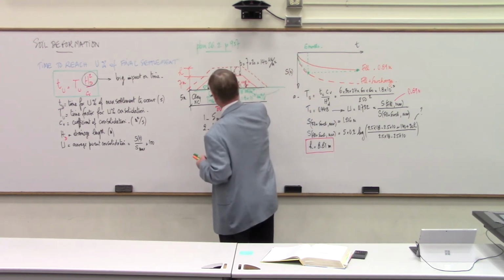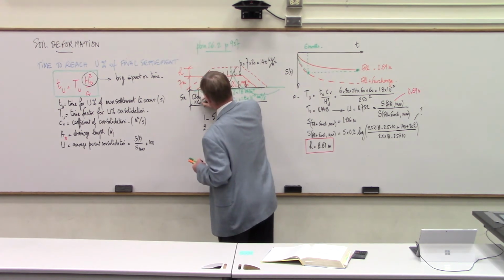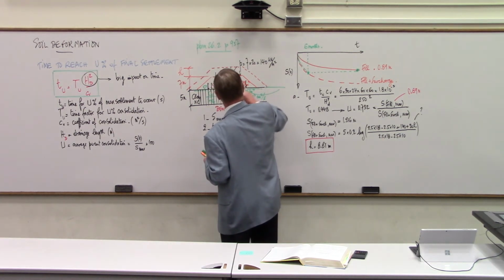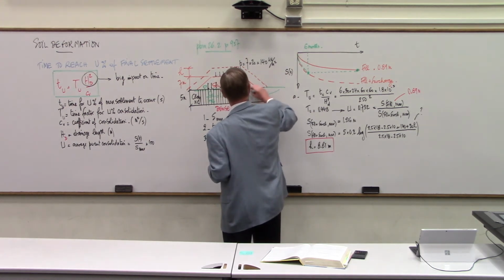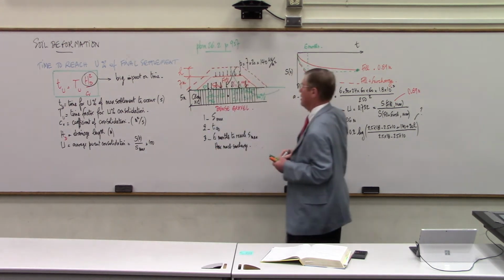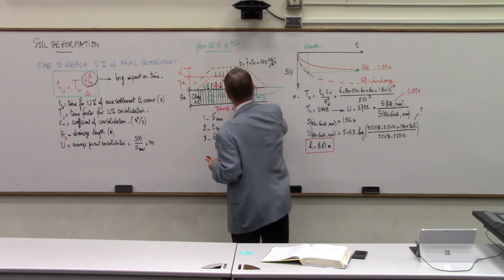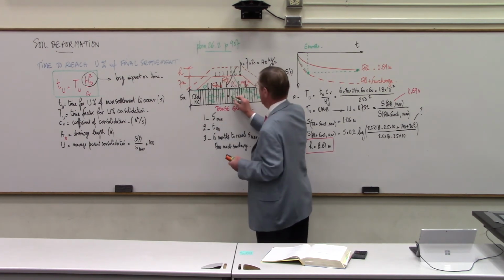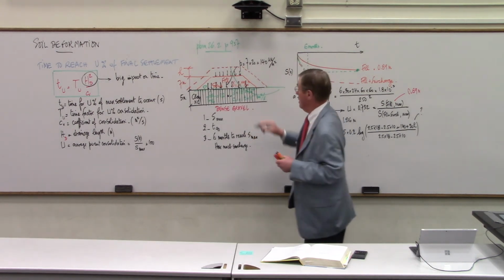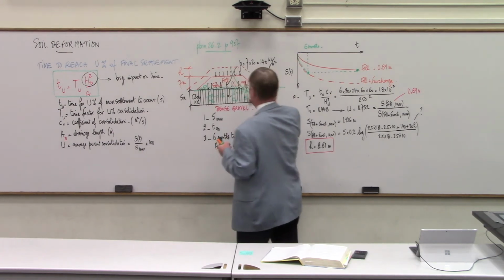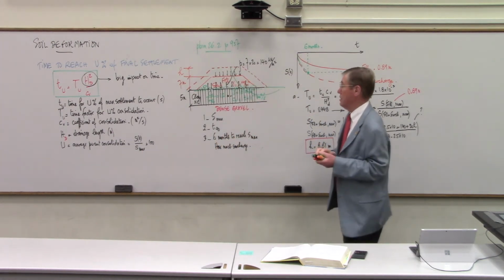So we put them vertically, and we make sure they're close together, like this. So each one of those is a wick, and you can see now that the water, which is in the middle between those wicks, only has to go either this way or that way, very little distance, and then go up the wicks and drain in a gravel layer at the bottom of the fill.